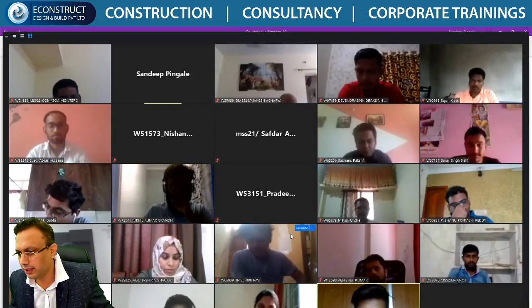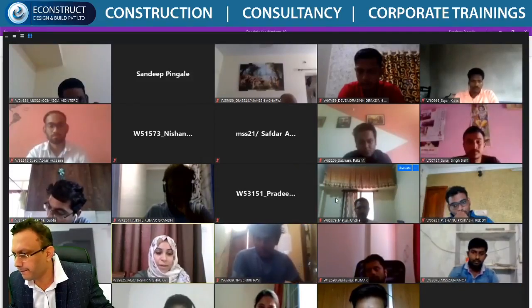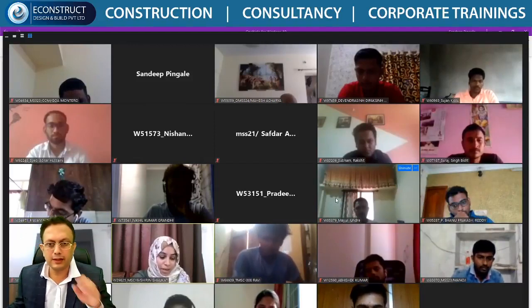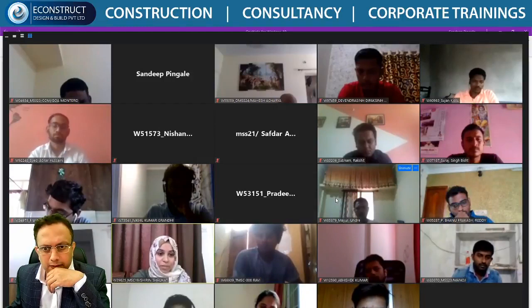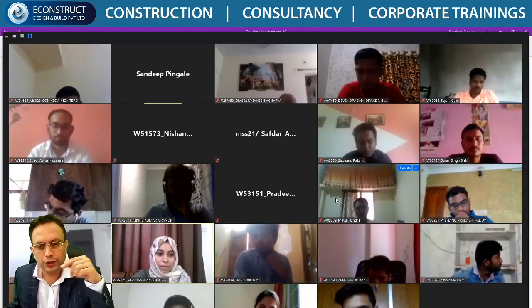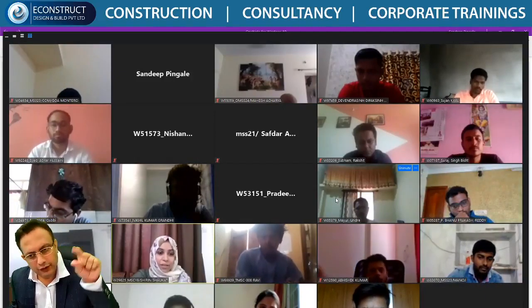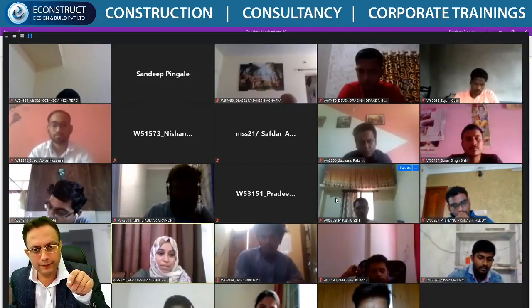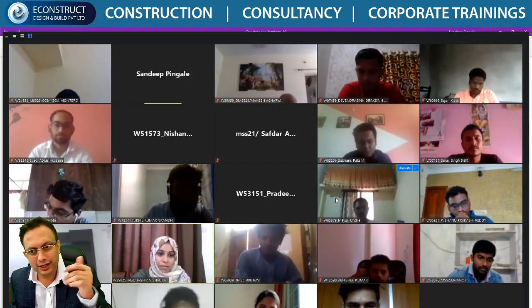Yes? Anybody? Any doubt? For release and action fixity for frame members, if we give 0, is it constrained or restrained? Like if we put 0 value, it acts as single supported or fixed. So you mean to say you are giving releases with the value 0? Yeah, if we give 0, constrained value or restrained value? So it is released. Released, yes.